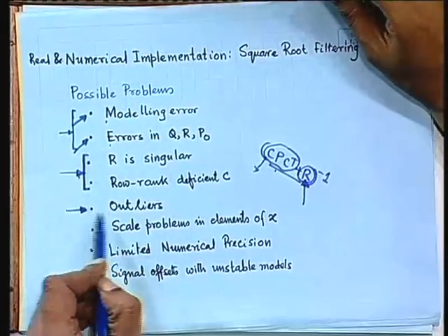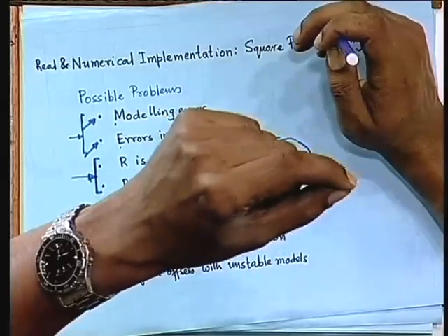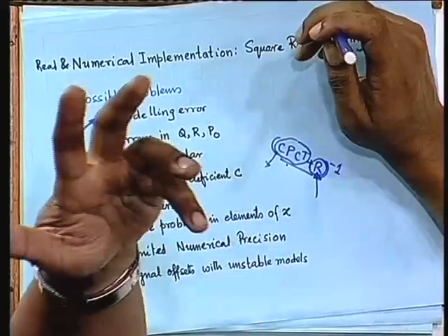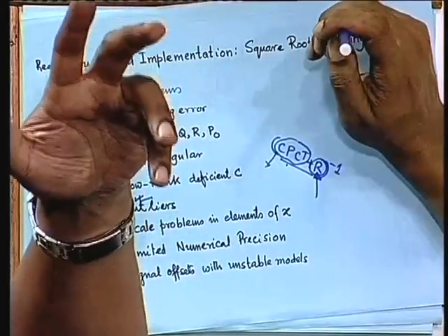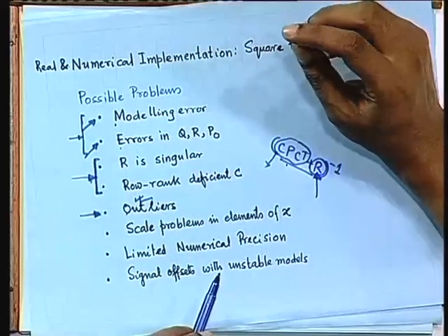If you update based on these outliers, what will happen? Your estimates will suddenly get a big shock. You are arriving close to the true estimate, suddenly one data point comes and shakes your estimate up, because the Kalman filter suddenly finds a very bad data point and considerably changes its estimate. So these things should be handled.